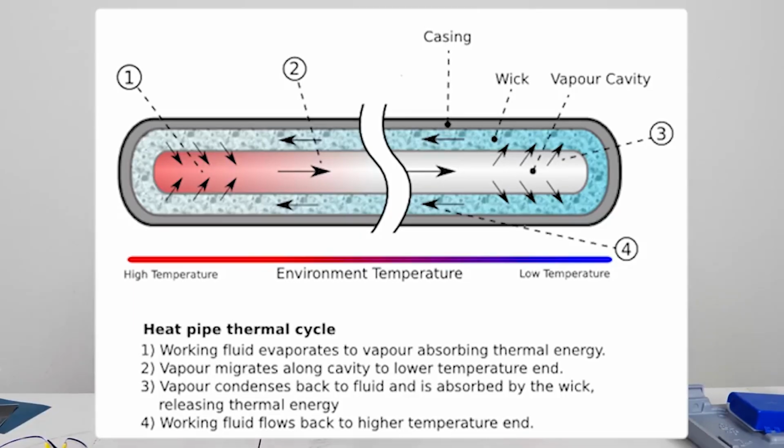And so it's this continually efficient heat pump that continually takes heat from one end of the pipe and pushes it to the other side of the pipe. And you can actually use different types of liquids and different kinds of metals for this, but this copper-water combination actually works extremely well. These are used in a lot of applications, including inside of computers. When you need to transfer a lot of heat quickly, these heat pipes are unmatchable with any other standard metal.